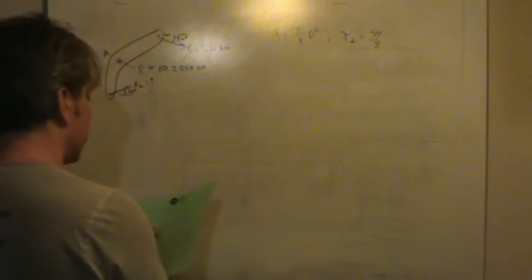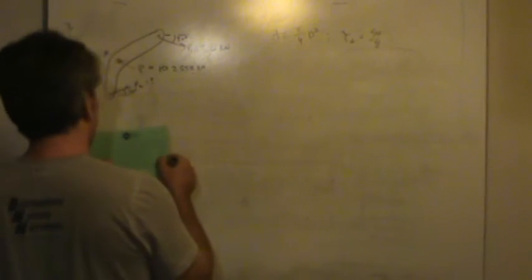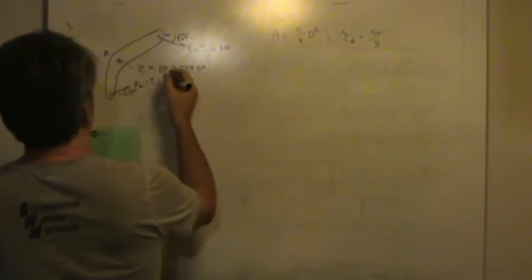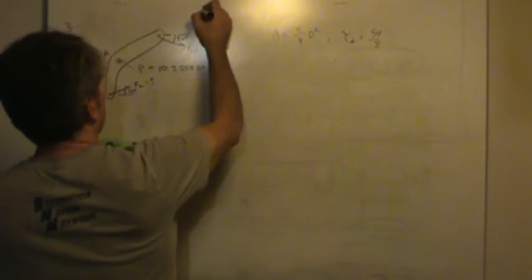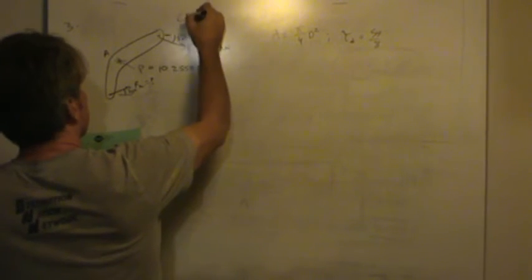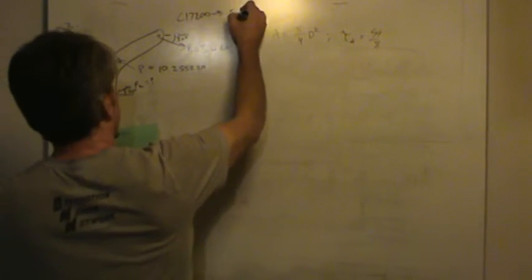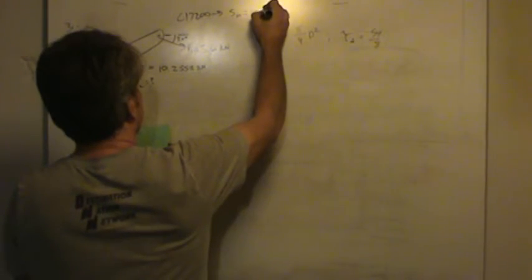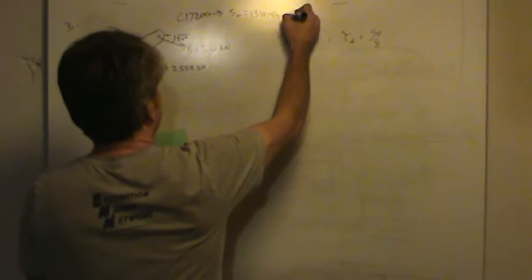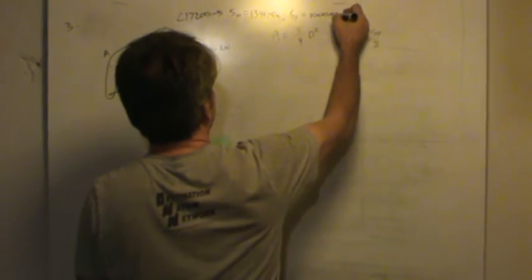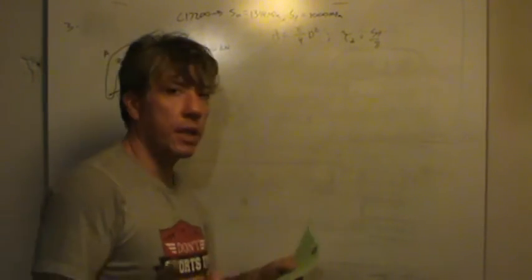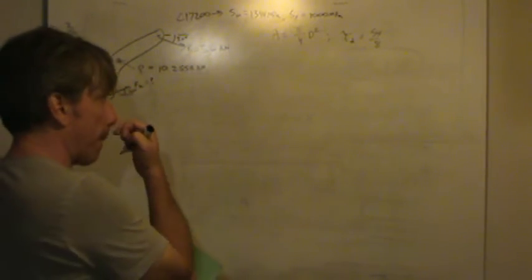So I thought, well, since we've got this beryllium copper, what properties does it have? Well, if you look it up, the material is C17200. The material has an ultimate strength of 1,344 megapascals, but it has a listed yield strength. The listed yield strength is a gigapascal, so 1,000 megapascals. Now, like I said, it also has that 4% elongation, which indicates that it's brittle. So what should we do here?